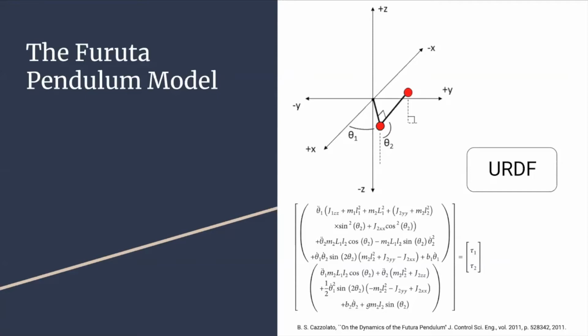The equations of motion for the system are below. The inputs on the right, τ1 and τ2, are the actuation in the shoulder and elbow respectively. However, as we will be using this as our underactuated model, we will only be providing input into τ1. This entire system was implemented as a URDF in our programming, which is a universal file format for describing physical objects. The parameters for the inertia matrices and masses were referenced from papers using this implementation.